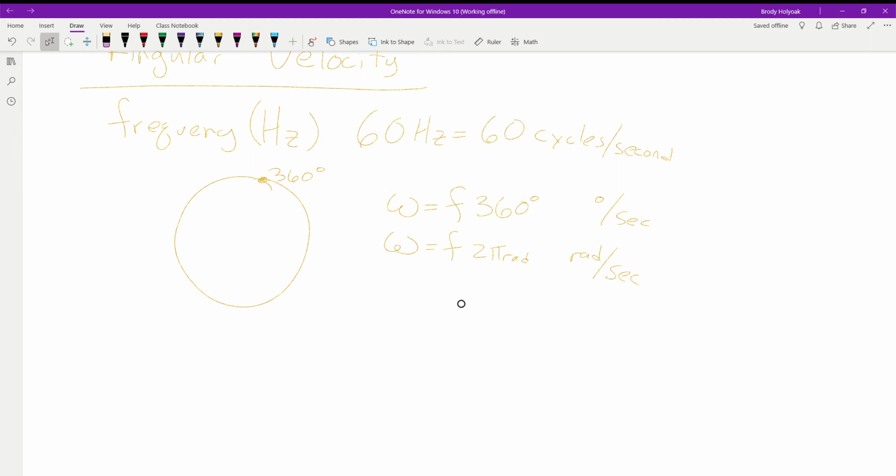Like they had a pie that maybe came over at 1.2 seconds, so it didn't quite set where it was supposed to. So when it brings it over and sets it down at the next station, it's dropping the filling here, but the pie shifted over a little bit, so it only gets half the pie filling. That's why this is important: we want to know the speed we can travel so we can know how long to tell it to move before we tell it to stop.